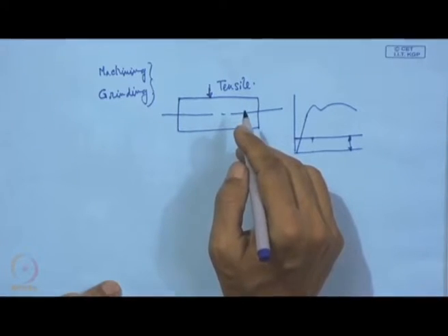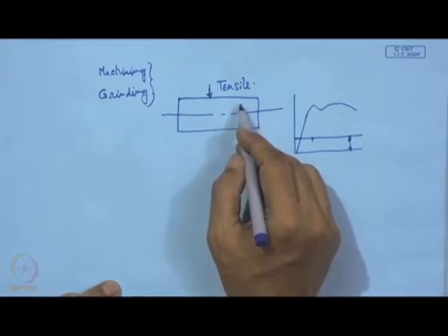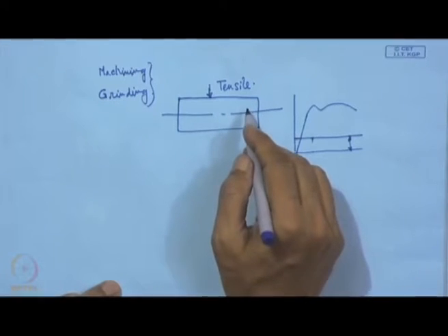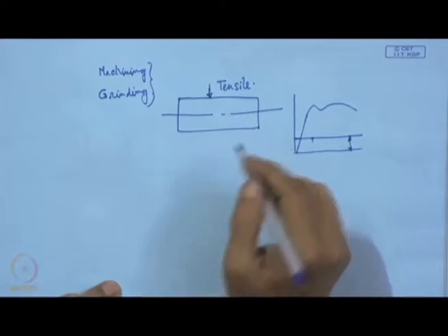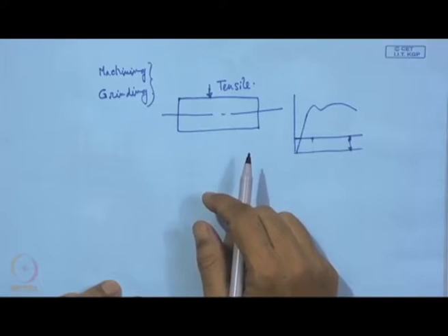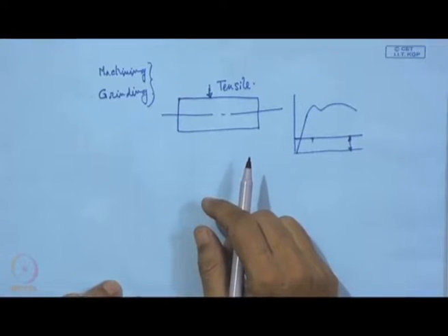Number 2 is that if we have some cold working on this surface, then there can be some strain hardening, and as a result of this strain hardening, surface hardness will increase. And number 3 is that by this plastic flow of the material, we can have a smoother surface, and all sorts of tears and cracks can be suppressed by this plastic flow.